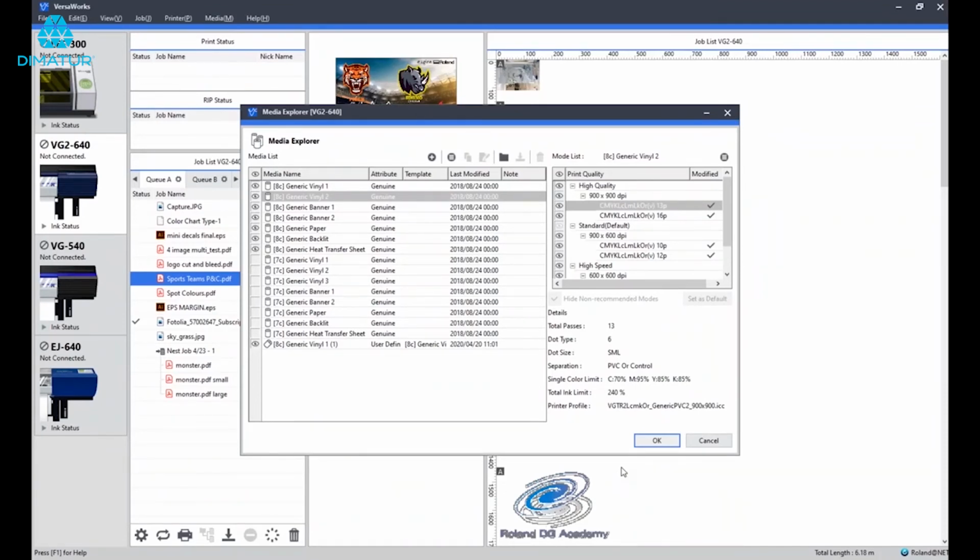Another question that came in, just bear with me a moment, I'm just going to read this one. There's a question about the printer color match settings, saying, instead of re-inputting the printer's color reference data at the start, can you not calibrate Roland machines to a color standard, say Fogra 39? We're going to be getting into a little bit more depth with profiling. Yes, you can calibrate your profiles to certain standards.